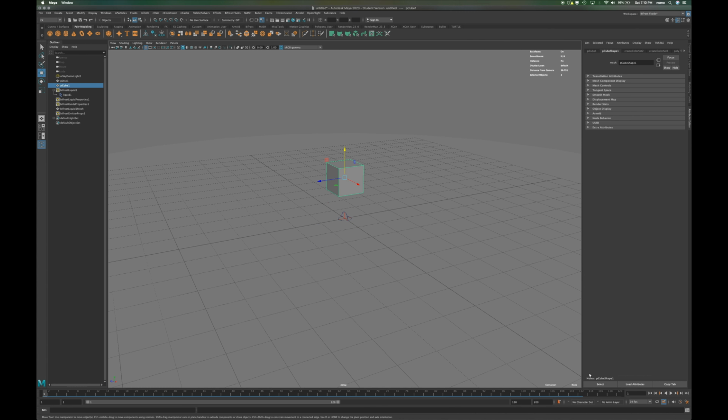I can choose my object. And now we're going to use the timeline just like we did with other liquid simulations or anything with the end particle systems. So I'm going to go ahead and hit play. And you're not going to see anything. There's a couple things we have to set first before you see it. It just kind of goes by because it actually did make a little iteration of fluid, but it was there for like one frame and then it was gone.